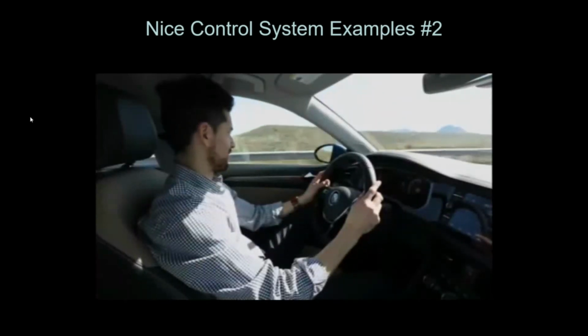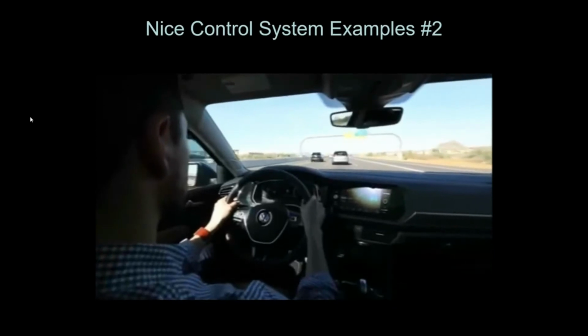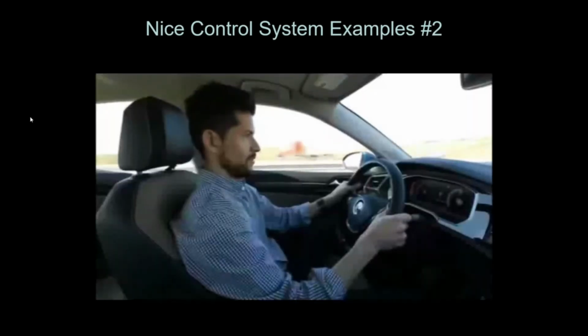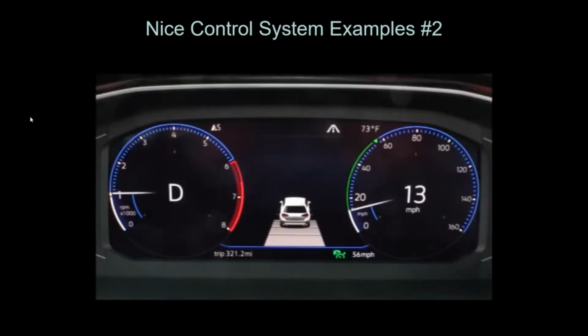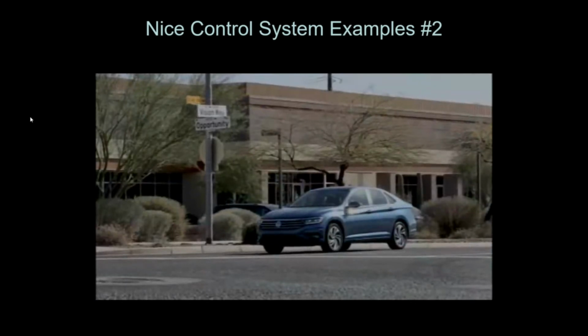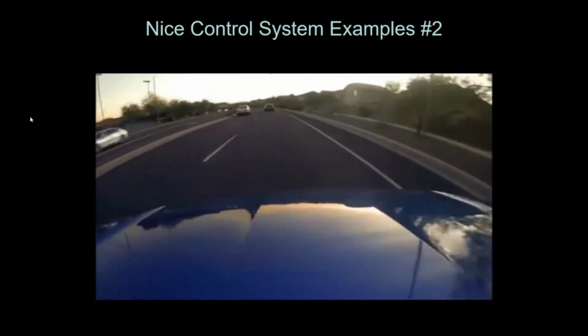When a slower moving vehicle directly ahead is detected, adaptive cruise control automatically slows down and helps maintain the distance that has been set. Once the slower vehicle moves out of the way, the system adjusts back to the set speed. If the vehicle traveling ahead brakes to a standstill, adaptive cruise control will also brake your vehicle to a standstill. The driver assist system holds your vehicle stationary, with the brakes and adaptive cruise control staying active. To drive off after being stationary, briefly press the accelerator. Adaptive cruise control will resume speed regulation as long as the vehicle in front is moving again.